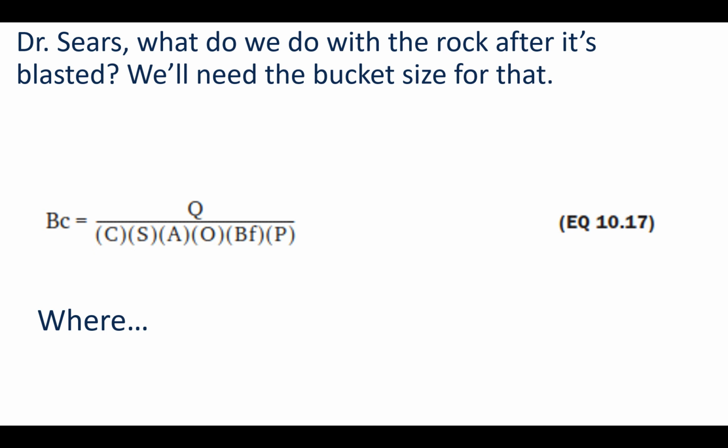So after we blasted all the rock, somebody's probably going to ask, we got to move it, right? And to do that, we're going to need to determine the bucket size. And bucket capacity is once again a bunch of variables, and they're listed on the next screen.